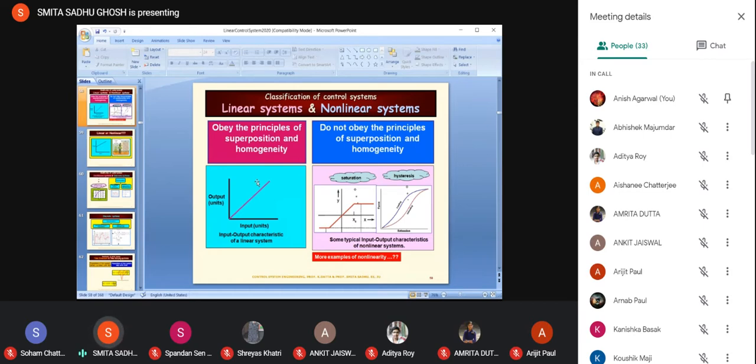So say, in the case of the first order system, I apply 1 unit of input, whatever your unit is. I'll get an output, whatever it is in the steady state. Now if I double the input, the output in the steady state should be doubled. If I half the input, the output in the steady state should be halved. So that is what I would have to look at, not at the response versus time plot, which is going to lead me in the wrong direction.